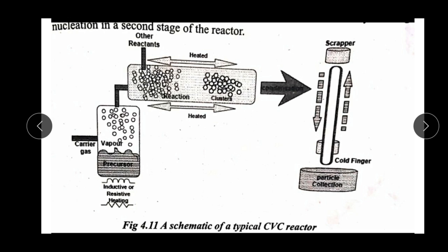By adjusting the residence time of the precursor molecules by changing the gas flow rate, the pressure difference between the precursor delivery system and the main chamber, and the temperature of the hot wall reactor, one can result in the production of nano-sized particles of metals and ceramics instead of thin film as in CVD processing. In the simplest form, a metal organic precursor is introduced into the hot zone of the reactor using a mass flow controller.